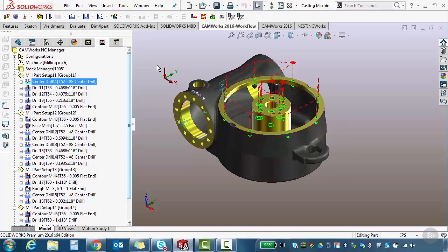So that's a pretty easy way to group like items together. I use that a lot if I'm roughing. If I use 1 diameter of roughing cutter, then what I'll do is I'll combine all of the roughing operations together. So I just go grab that 1 rougher and I go rough everything that I possibly can in the current setup that I'm using.